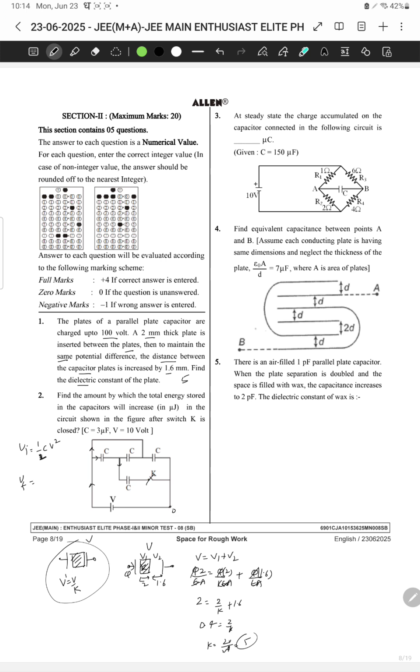Let's say if I say it is 0, 0, 0, it is V, V. Let's say it is X, it is V. If I draw the equivalent diagram, between V and H there are two capacitors in parallel. Between H and 0 one capacitor, and between V and 0 there's one capacitor, and there's a battery here. So these two are in parallel, C plus C, 2C, and 2C in series with this one gives 2C by 3, plus C, which makes it 5C by 3.